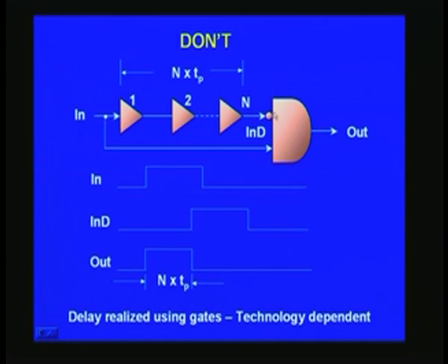This is inverted here and fed to the gate, and the input is also fed to this gate with a view to get a positive pulse from the two inputs that we have here. And this input is basically from, as I said, a push button switch.